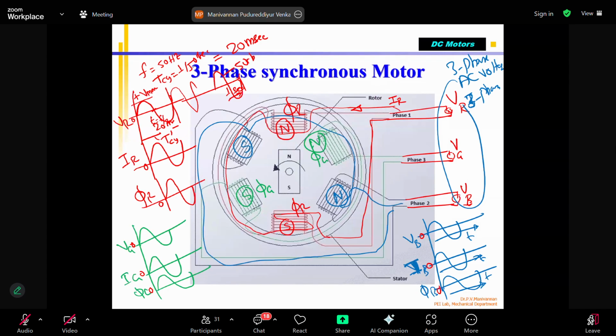Okay. So it is the same for all three, but please note that in three phase, the red, green, blue voltages are increasing exactly the same. If this voltage is say 200 volts, this is minus 200 volts. This is also plus 200 volts. This is minus 200 volts. All three phases will have the same voltage, plus 200 volts, minus 200 volts. The only thing is, where they reach the peak is shifted by 120 degrees. I am going to talk about that in the next slide.